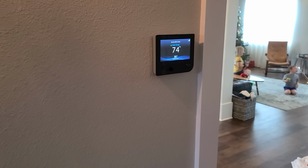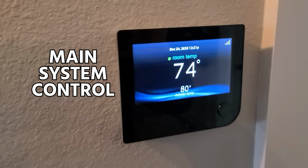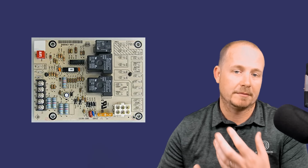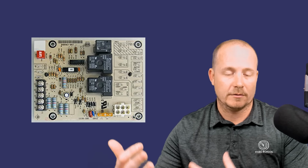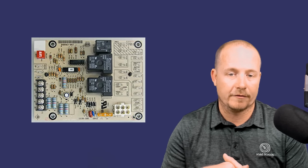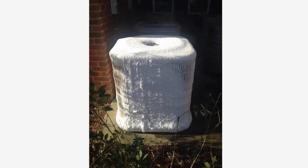Like we mentioned, you have your thermostat, which acts as your main system control for comfort, so it turns the equipment on and off and in the proper modes. You have your blower board, which controls your blower. Sometimes in variable speed applications, it will also control the speed of your blower at different stages and under different circumstances. And on the outside, you have your defrost board, which is in charge of controlling that outdoor unit, especially during defrost. So when there is ice on that outdoor coil, to get that off during heating mode.